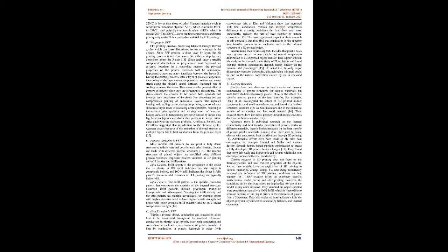In FFF printing, a solid thermoplastic filament is melted and then extruded onto a bed to create a two-dimensional layer. The extruded semi-liquid polymer solidifies almost immediately after leaving the extruder. Layers are printed on top of previous layers repeatedly to create a three-dimensional solid object from the digital design. In FFF printing, one of the most important qualities of the filament for it to be extruded through the nozzle is the ability to melt or soften at high temperatures, which can cause some difficulties for freeform features. 9.